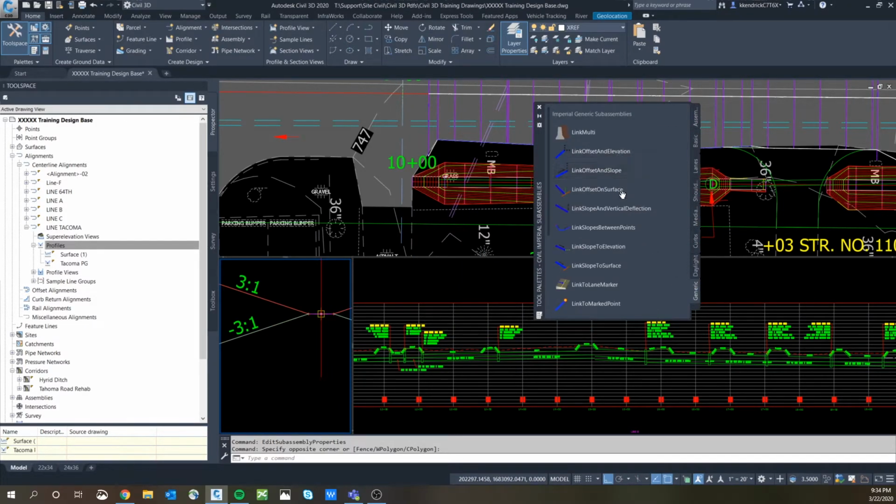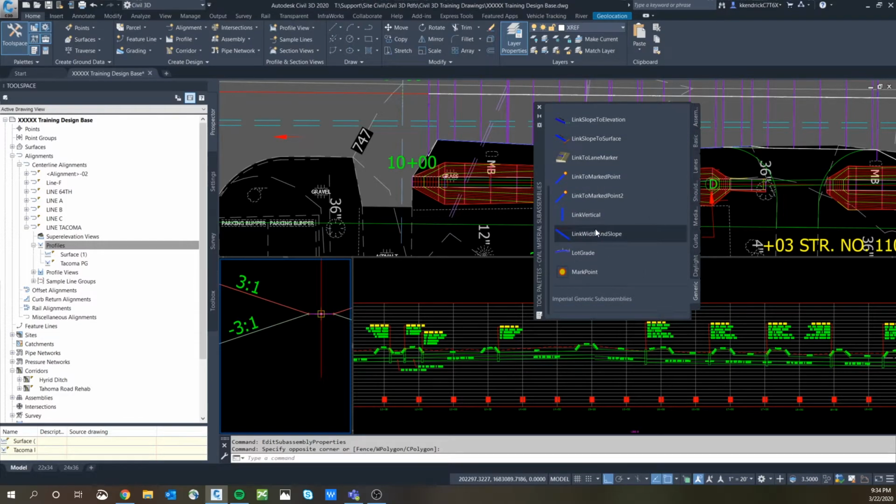There's all these different options for just drawing a line. Kind of a, it's got every option you can think about. Vertical, length, width, and slope is the one that I like to use when I'm creating ditches, or the line that gets you over to the ditch off of the edge of the shoulder if you're needing to get down at 3:1 to a ditch design grade. I use those.